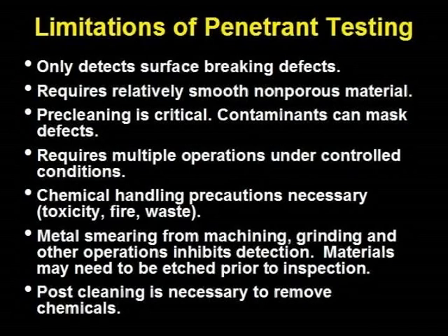Penetrant testing has the following limitations. Penetrant testing only detects surface breaking defects. It requires relatively smooth, non-porous material. Pre-cleaning is critical. Contaminants can mask defects. Penetrant testing requires multiple operations under controlled conditions. Chemical handling precautions are necessary.